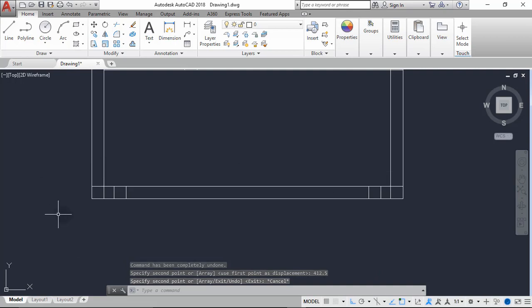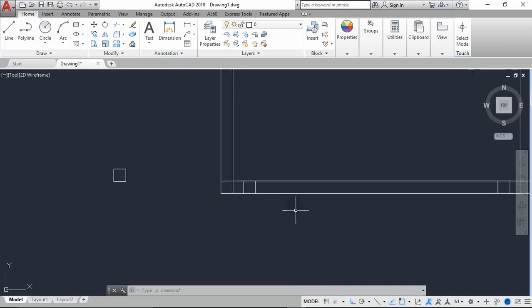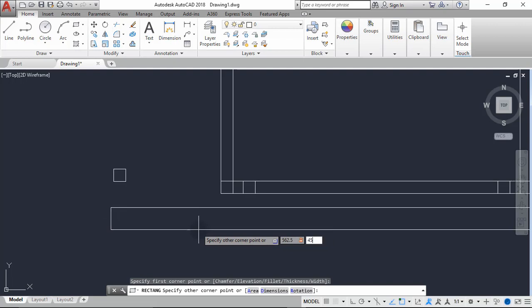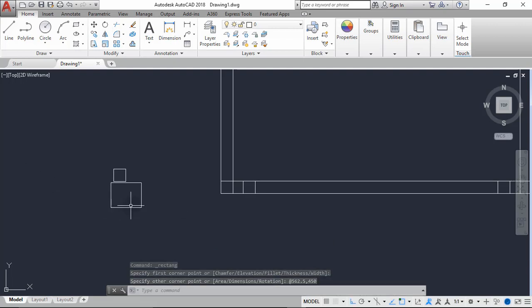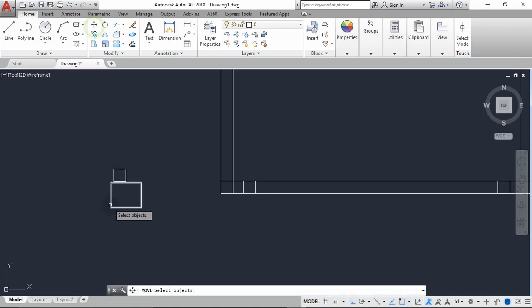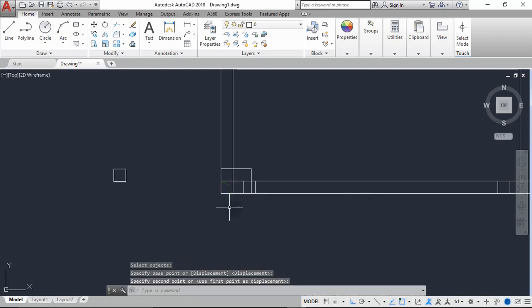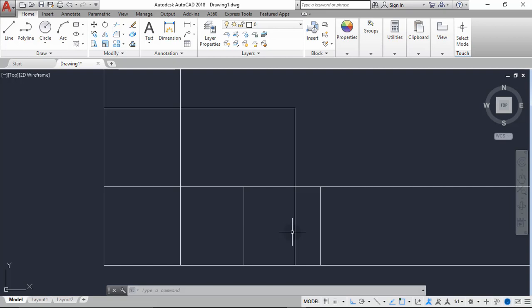After that, we'll create the base for our column. The base for this column now will be 450 by 562.5. Pick another rectangle. We do 562.5, click tab, 450 and hit enter. We have this base. We now need to move and use this point. Drop it here. As you can see, that means we have a dimension error around here in our placing of the column.